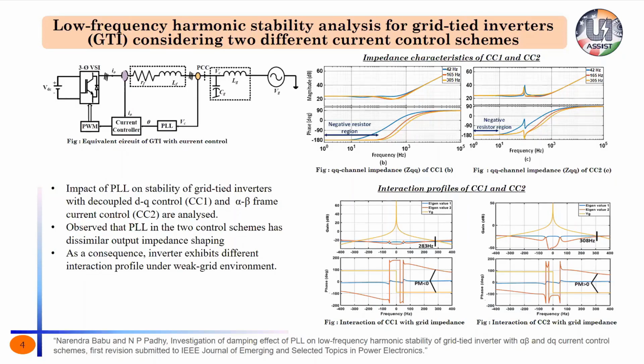Whenever we talk about impedance interaction from a basic electrical point of view, we always remember it as a resonance occurring between two passive elements. The stability of this resonance depends on the damping offered by the passive circuit, right? Damping can be either positive or zero in passive circuits. If damping is positive, the system will decay with respect to time. And if damping is zero, the system will oscillate. This is what we have seen in passive circuits.